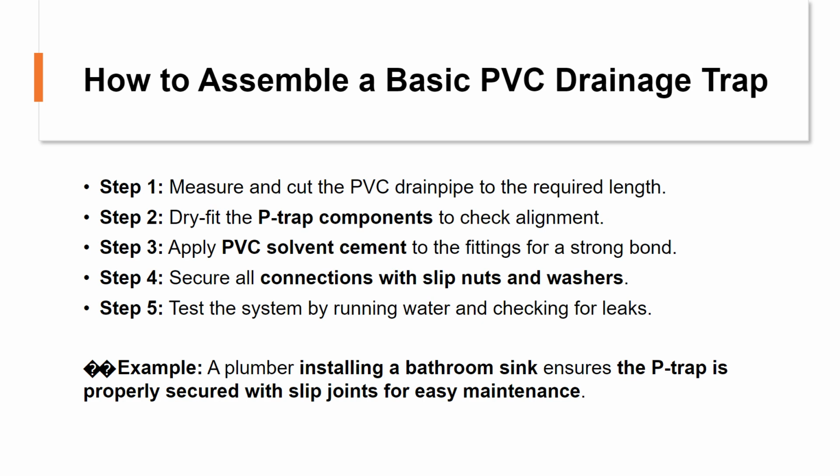What you'll need: PVC trap, P-trap or S-trap, short length of PVC drain pipe, pipe cutter or hacksaw, sandpaper or deburring tool, solvent cement and brush, gloves, and a clean work area.